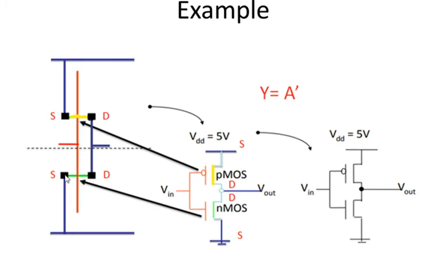Now to connect different kinds of layers or different kinds of material, we need to use a contact cut. This is the contact cut used to establish electrical connection between the metal and the P diffusion. Likewise, here also we are connecting different kinds of materials, so we need to use a contact cut to provide electrical contact between N diffusion and the metal.